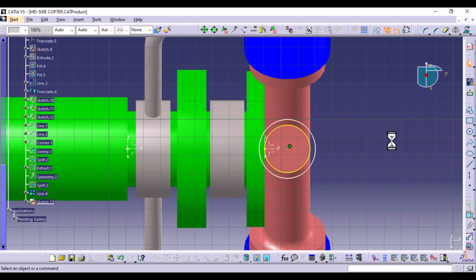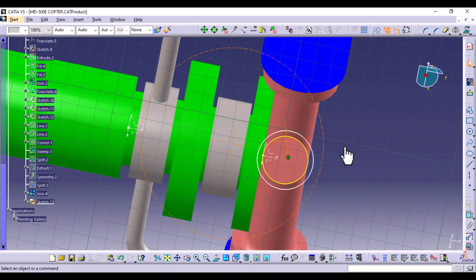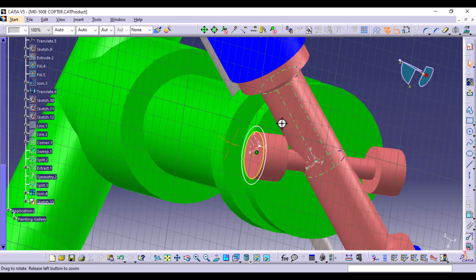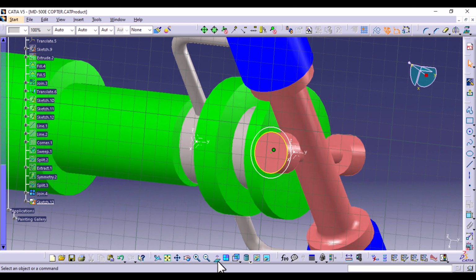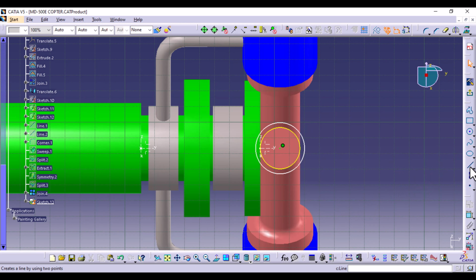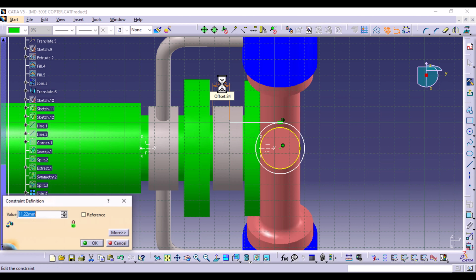Like so. And then we have straight lines that are going towards the side where we are connecting it. So this is on this side, so it's going to go to that side. So select line from this center point, and it's going to be tangent, okay? And then it goes up to probably the middle section of this profile. That means that the distance between this endpoint and this edge is going to be 10.